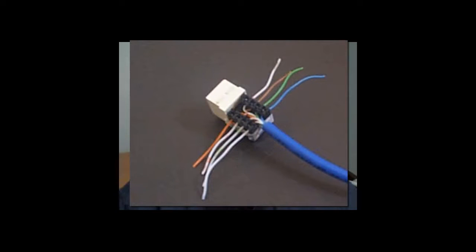A similar process occurs at the jacks, either in a wiring closet or on a patch panel for each jack, or perhaps in the back of the wall office jacks so that we have convenient access to our desktop computers. Each company makes a slightly different jack, but remember that we're following the 568B standard. It will show you where each of the 8 wires will go by color.